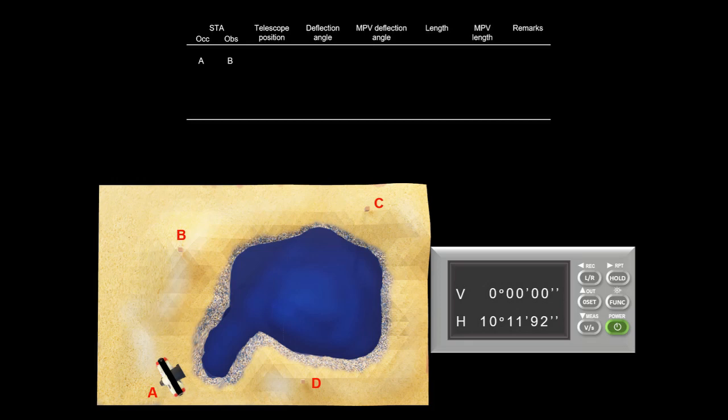Before you do any angle readings, make sure that the theodolite is perfectly leveled and centered over station A. Afterwards, determine the bearing of the first line, which is line AB, by referencing your theodolite towards the magnetic north using an external compass and by pressing the zero set button twice. In this manner, you will notice that the horizontal angle reading in the LCD will be reset and will indicate 0 degrees. Aim for the station B using the telescope.